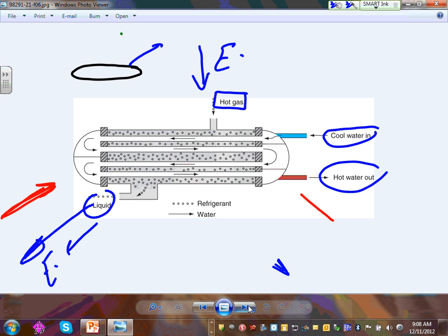And then, believe it or not, if that's not enough, they use a cooling system to cool the refrigerant. So a cooling system to cool another cooling system. So it gets more complicated. The idea is you want to remove energy from this gas, fast and efficiently. The easiest way is air, but for bigger systems, it becomes very expensive to use air. So they use a cooling tower. They circulate the water with a pump, cool the gas.